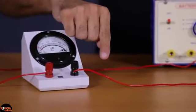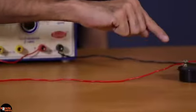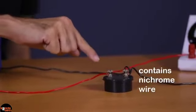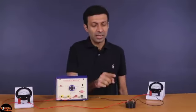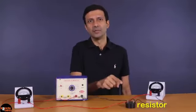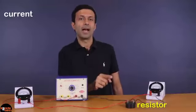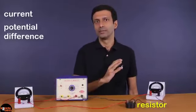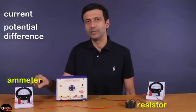And the ammeter is connected using this wire to this black box. The black box contains a nichrome wire in it through which current can pass. This is usually called the resistor. We are going to measure the current passing through the wire in the black box and the potential difference across the wire. To measure the current through the wire, we will use this ammeter.